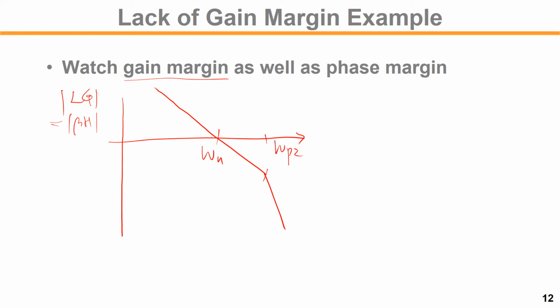Typically this kind of 20 dB per decade, single pole roll-off is the expected response, but sometimes a student may see this kind of zero response, and then it follows like this, or any pole will get there. So if you look at this quite long frequency range, it doesn't go down, doesn't follow the 20 dB per decade slope of single pole roll-off, it just becomes flat. So in that case, for example, you see the gain and the phase here.